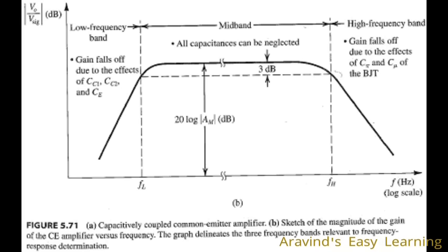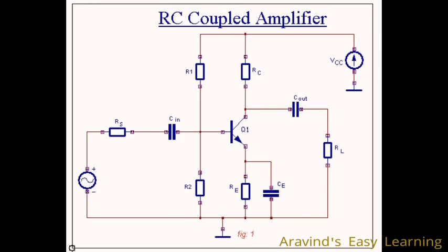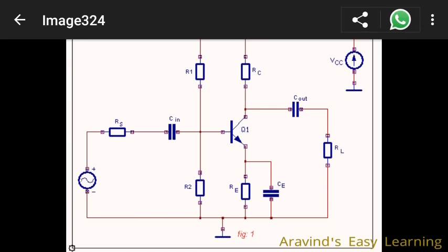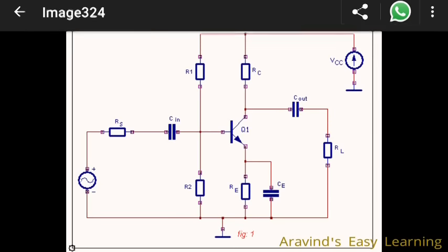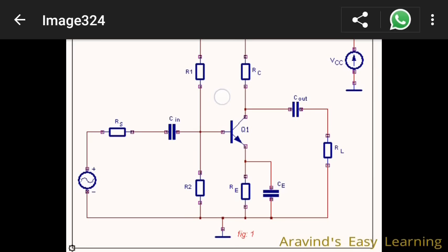What about high frequencies? See, at high frequencies, there is some other factor known as the inter-electrode capacitances. Inter-electrode capacitance, what is that? See, look at this. This is a conducting path. This is another conducting path. Or we could say this is a conductor, this is a conductor. Okay? This is air. Conductor, air, conductor. Sounds familiar? Exactly. This is a capacitor.